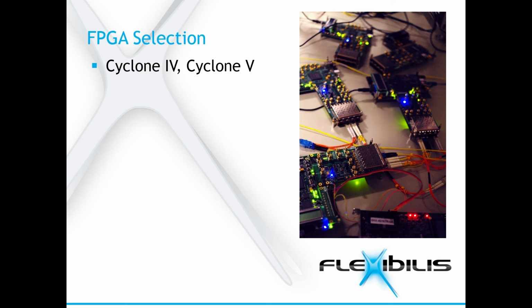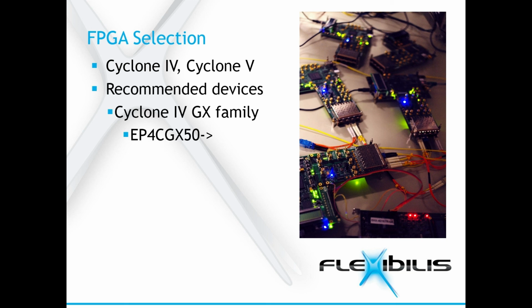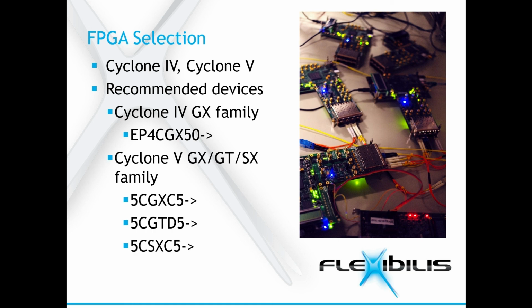The recommended devices from Cyclone IV GX family are EP4CGX50 or bigger. From Cyclone V GX, GT, and SX families, from 5CGXC5, 5CGTD5, and 5CSXC5 upwards.